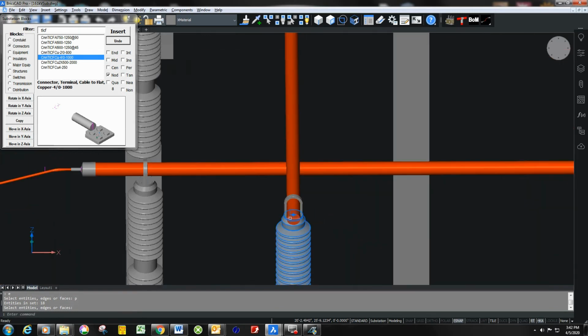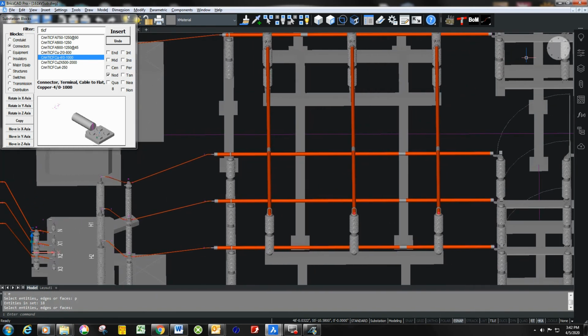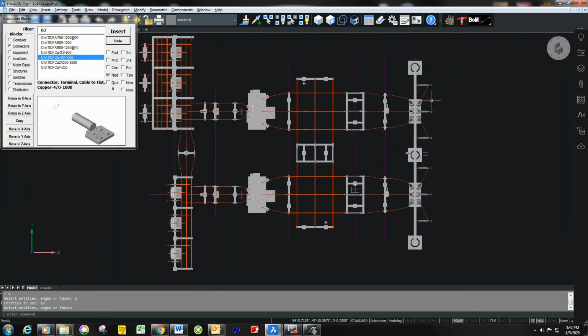So you want the end caps on the ends of all of your open bus, and the idea here is you want to keep the birds out, and if you can keep the birds out, then you can keep the varmints from climbing the structure to get to the birds, particularly snakes, who seem to have a knack for somehow stretching out across the tallest insulator in the substation and shortening it to ground. So we're going to do end caps, and again the command is simply end caps. It will go through and again highlight all the bus segments that get end caps.